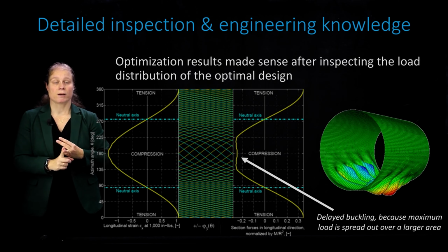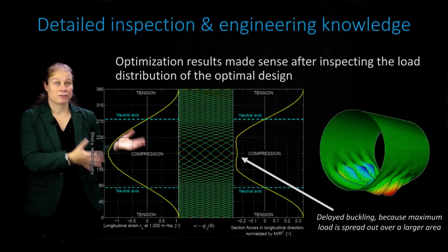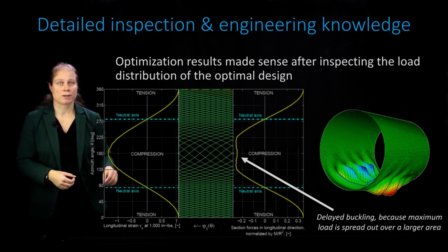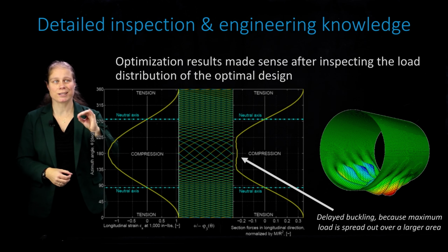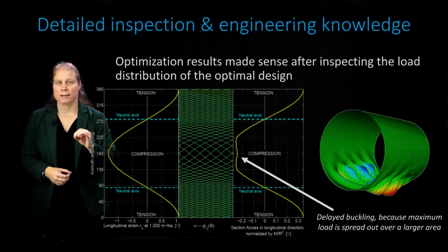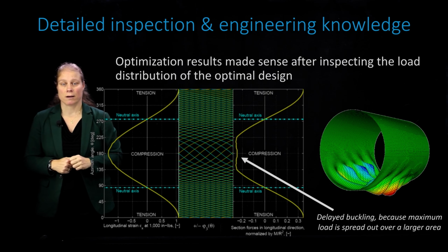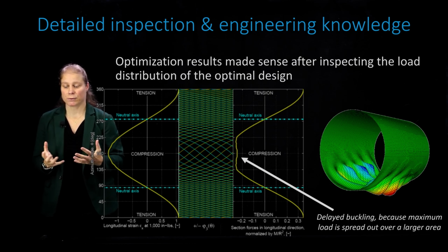And I looked at the buckling modes to draw the conclusion that this result actually does make sense. And so it wasn't just looking at that one buckling number that was better. It was really looking at all the information I had available to build that confidence.